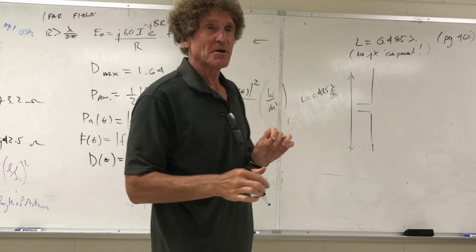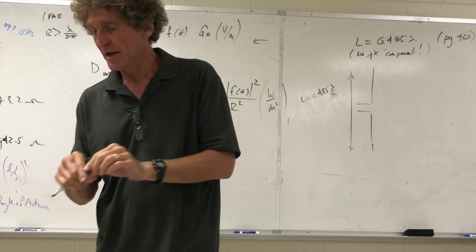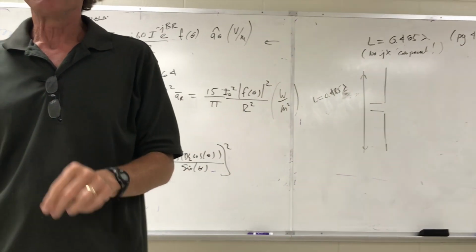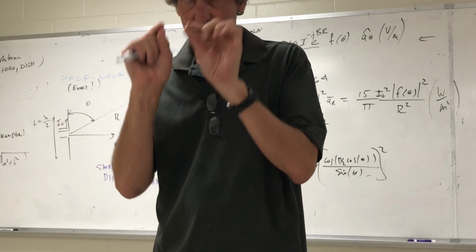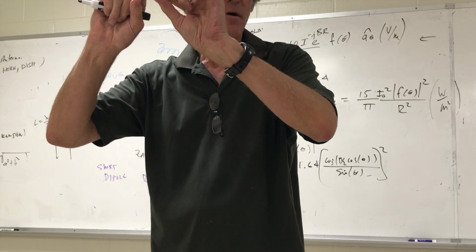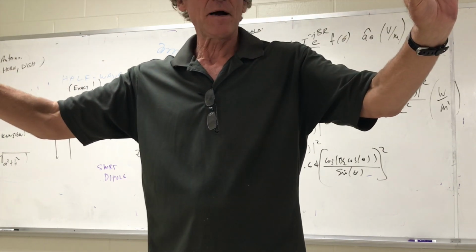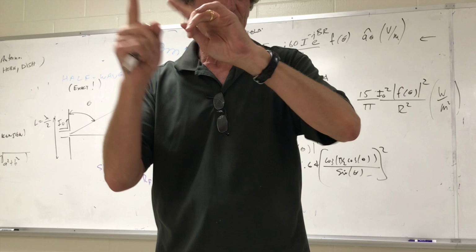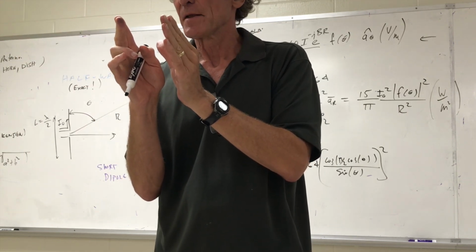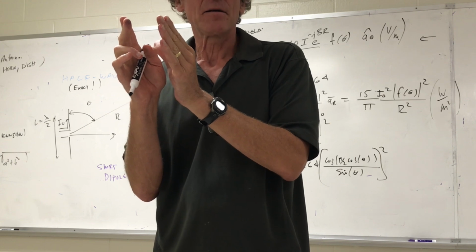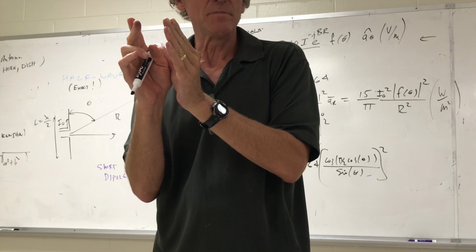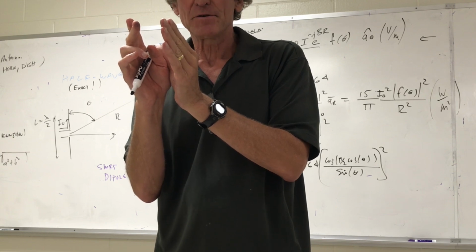And one of the tricks you can probably do is, if you take 2 pieces of wire, and then take a yardstick, or a meter stick, and pull them out so you have half a meter this way, half a meter this way. Take that, let the length, 1 meter, be half a wavelength. Wavelength itself is 2 meters, right? From 2 meters, you can figure out the frequency.